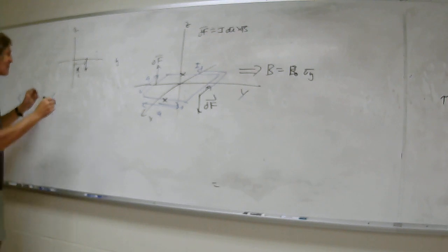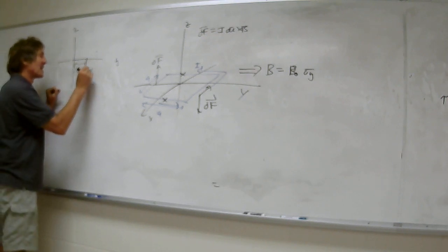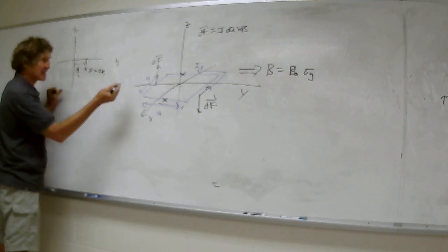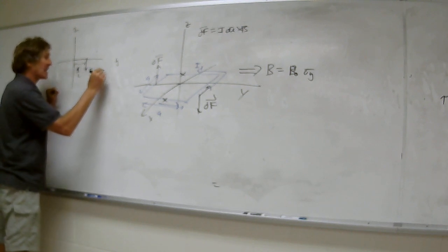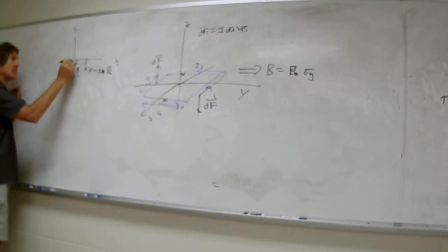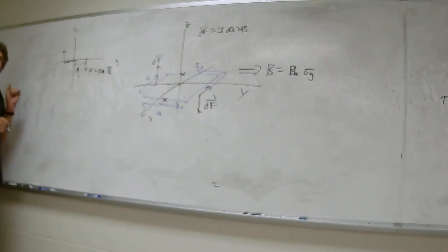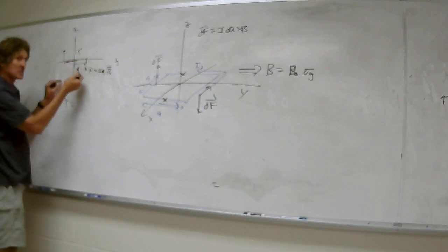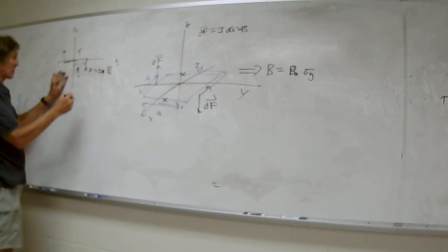All right, so this force is equal to I, L, and it's going to be IA in this case because I made it IA times B, right? Now, do you agree that there's the same exact force in the opposite direction, and it's causing the thing to rotate in the same direction? Do you all agree with that? That means the actual torque here would be equal to 2 times the actual torque on 1.